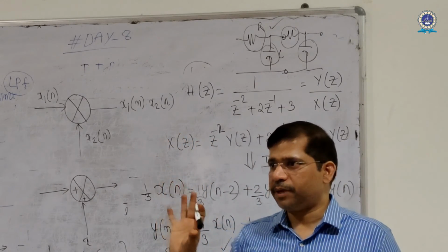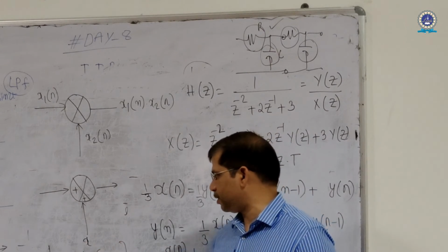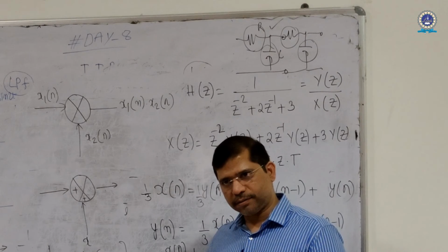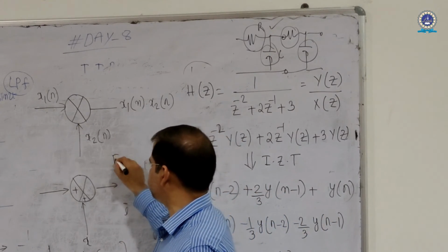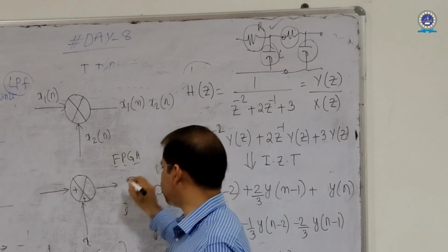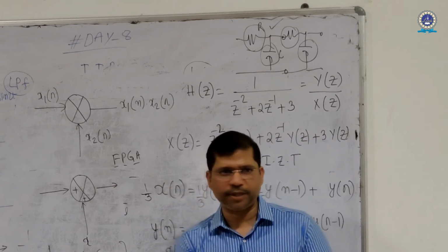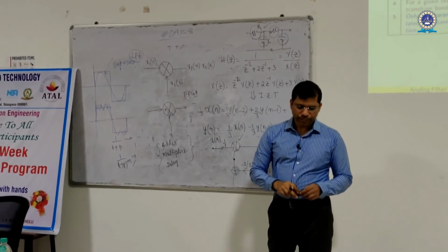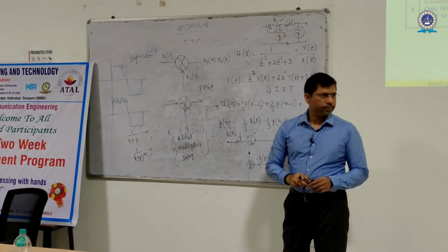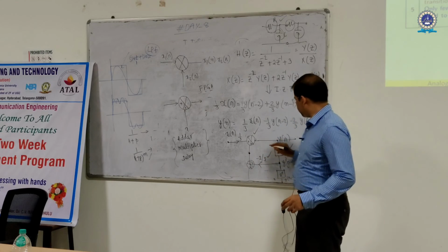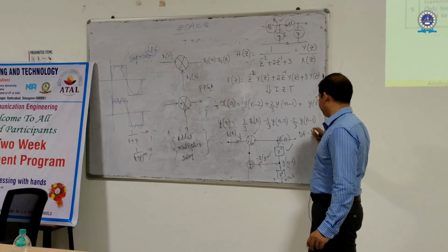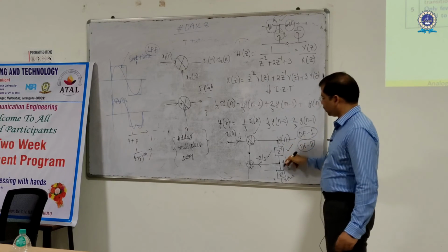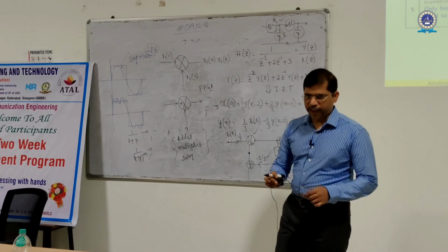There are a lot of problems in designing this RC. That is what people actually say, that analog design is tougher than digital design. Though you have first taken some kind of approximation, finally we are done with a simple adder, multiplier and delay, which these 3 are easily available in any FPGA. So you take an FPGA, all these things are easily available. You just have to write the Verilog code or whatever it is, and then dump it. This is normally what we call DF1, but similarly you also have the DF2 technique, wherein you reduce the number of adders as well as the delay.